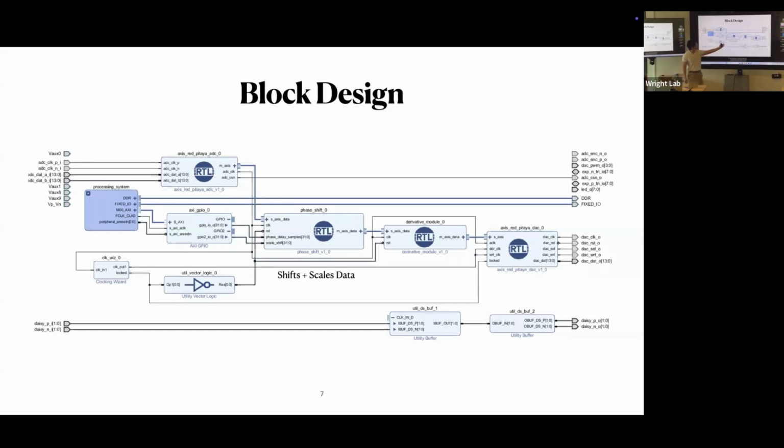And then these are the two modules that I've been messing around with. Since we have some sort of nanosphere and we get the motion back, we want to be able to scale and shift this data. Also, since we have the position, if we take the derivative, we can find the velocity. And so we know how fast it's moving, and using the scale and the shift, we could apply a force that's proportional to the velocity. And then finally, once we do the calculations, we could convert it back to analog data that would send out a voltage and push the particle.